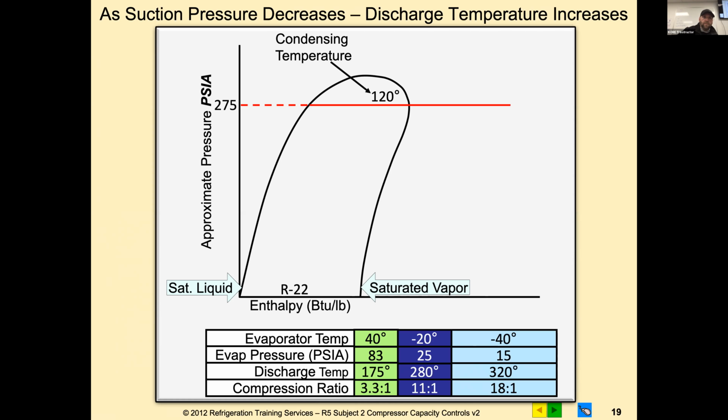One of the things we're finding is that on this particular application, the original condensing unit was actually oversized, which wasn't noticed until we swapped the condensing unit and started running into problems with high discharge pressure. So we really had to decrease our superheat a little bit further than what it was. We actually tied 2 of the evaporators into one condensing unit to compensate, because it was a compression ratio issue.